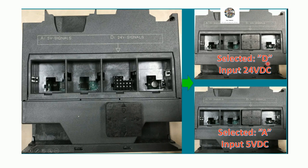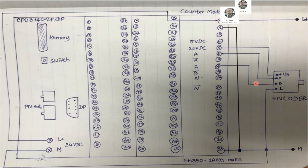If we select D, it means input 24 volt DC, and if we select A, it means input 5 volt DC. In this section I will select D. This was just an explanation of how to select the hardware configuration function for the encoder and how to wire it. Next, we will create the new project and then test with the real PLC. So let's go.